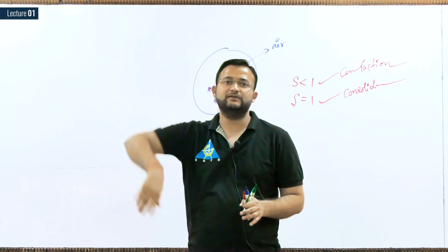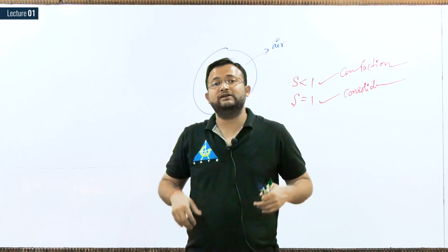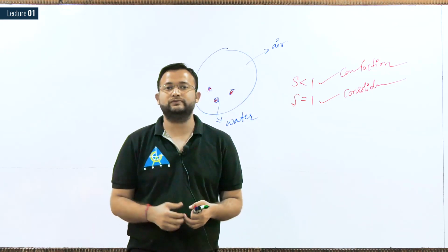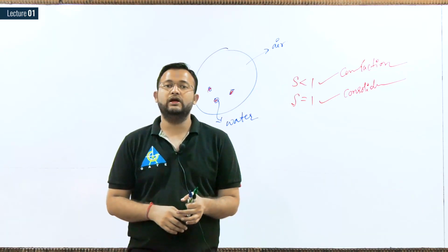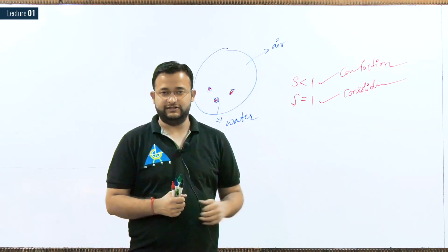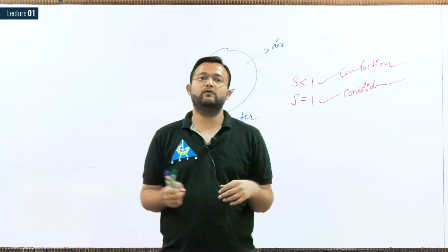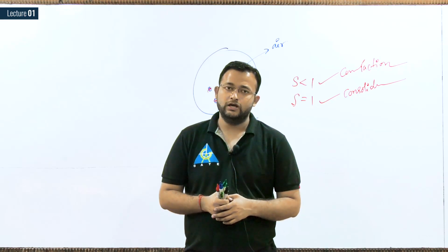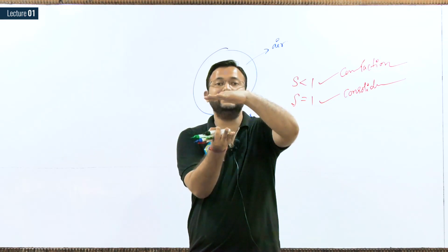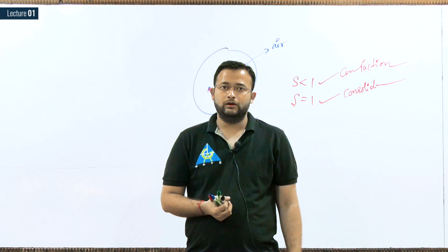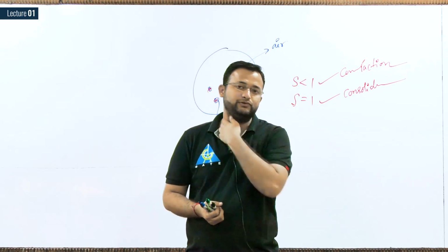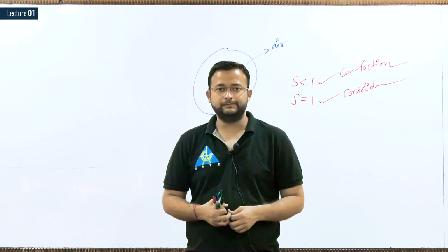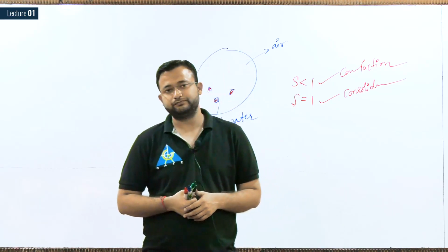So after 100 years, whatever pore water pressure develops, whatever excess amount of water was present, that can be removed from the soil, the process we call consolidation. Your volume of soil is reducing with time because of the self weight of your building. Clear? The process we call consolidation.